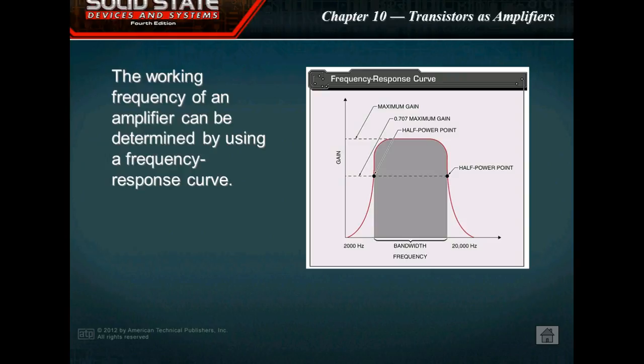Now remember, voltage and power vary with the square, right? Y'all understand that concept, right? Y'all ought to. I teach that a lot. I think I'll put that question on the next test: if I double the voltage to a circuit, what happens to the power? And see how many people in this class say it's going to double. It would actually quadruple, right? Because it varies with the square.